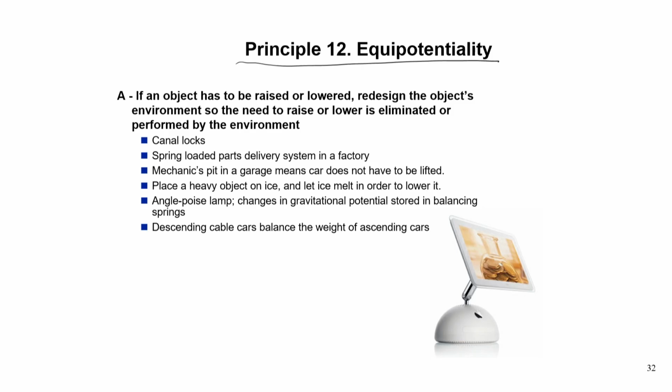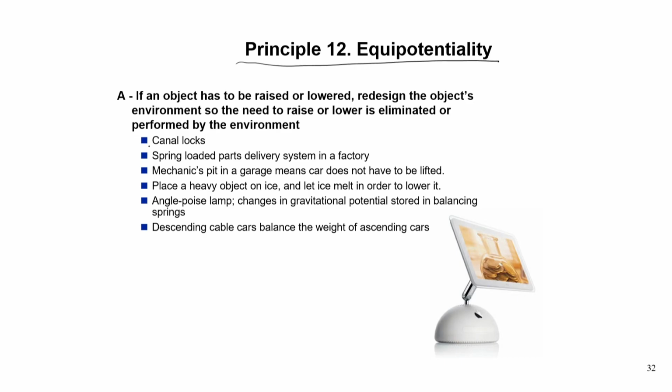today, but for the canal based transportation, let's say the Panama Canal, if you see, then you would see that there are a lot of slope changes, and the way they do is that a ship comes to a particular point, then they lock the downstream and then they increase water. So, because of hydraulic pressure, the ship also starts to go up. Once it reaches the perfect level with the next level of water, then the next upstream lock goes down and then the ship moves. That is the way the canal locks beautifully work. You look into YouTube, Panama Canal movement, etc., you would see such canal locks.